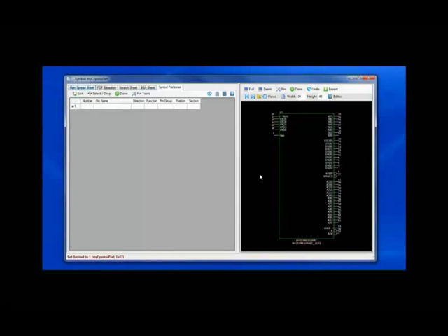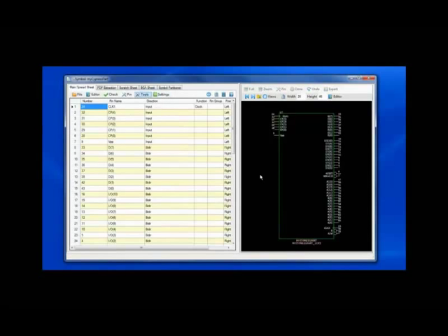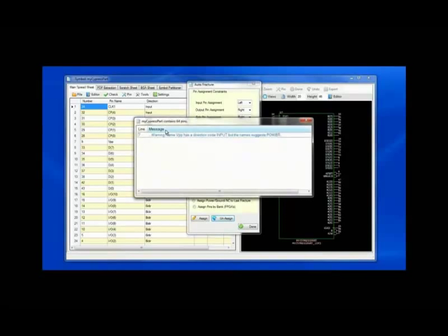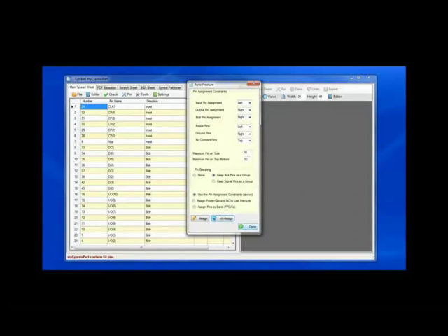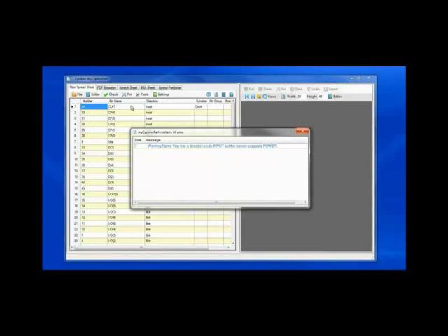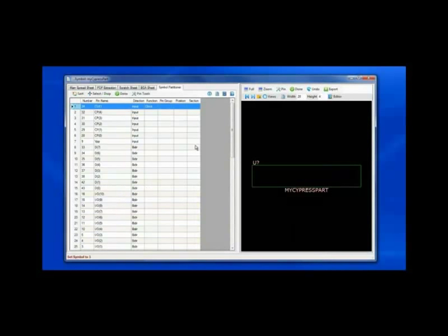Let's move back to the assignment and unassign the symbol set pins, and we will use the interactive placement to interactively place the pins in the exact XY position. Moving to the symbol partitioner, I just simply click on select and drop, and then I drop the pins from the spreadsheet to the symbol model.